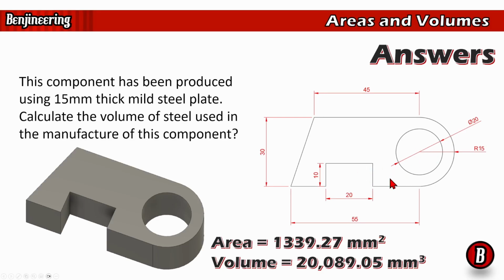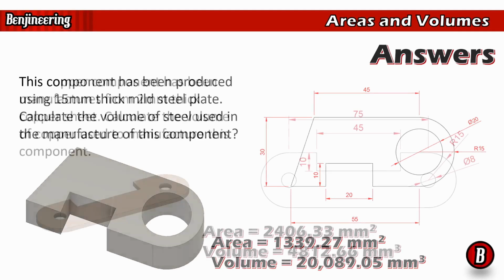Let's have a look at the second one. Actually, before we do, the thing that trips up people here, there's two things that were the big trip ups. Number one was being given the diameter instead of a radius. And the second one is people will calculate the areas of these two shapes here, but instead of taking them away because they're cutouts, they'll accidentally add them on. All right. So just be careful that that's not something you did and hopefully didn't do in the next example.